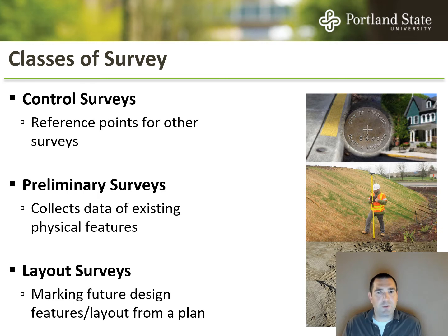So I think I have a photo a little bit later on as well where a grading piece of equipment, like a bulldozer basically, has two GPS antennas on top of it, and we can actually apply surveying workflows to automate where those pieces of equipment are going to grade and what elevation they need to grade at. So we can actually start controlling equipment using surveying techniques to automate them, very much like we're seeing with other automotive spaces as well.